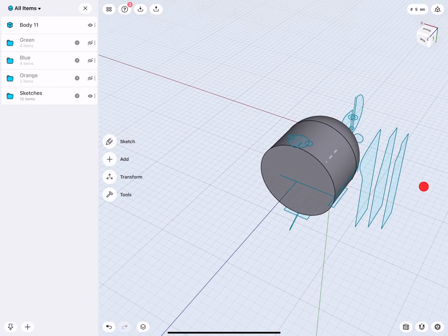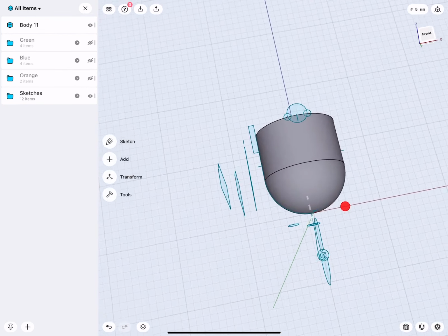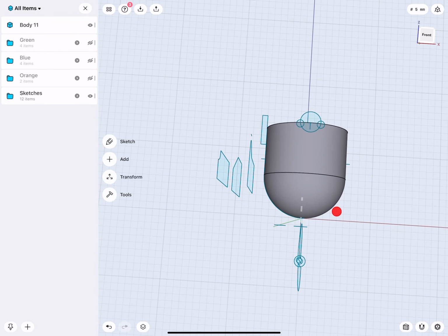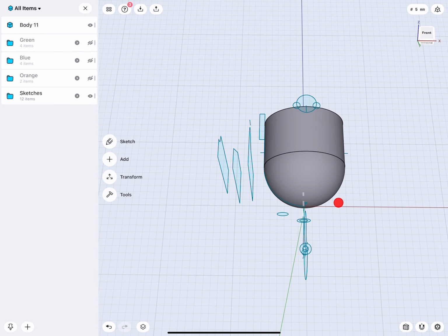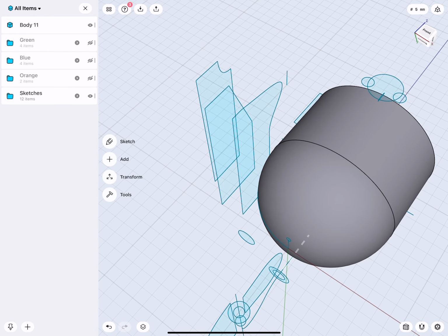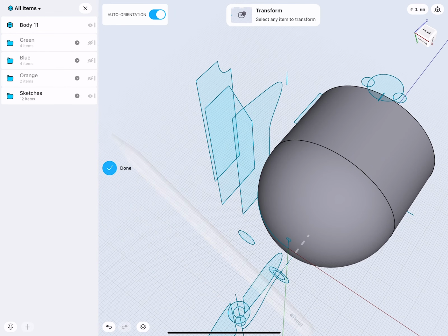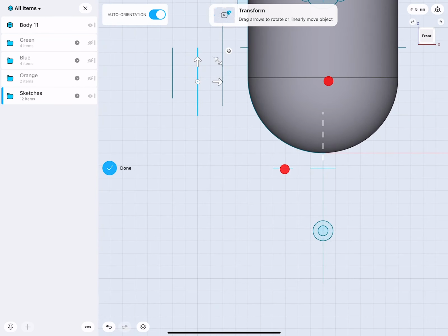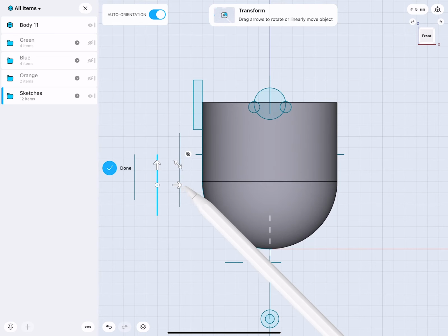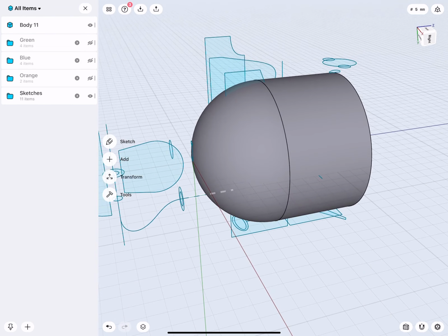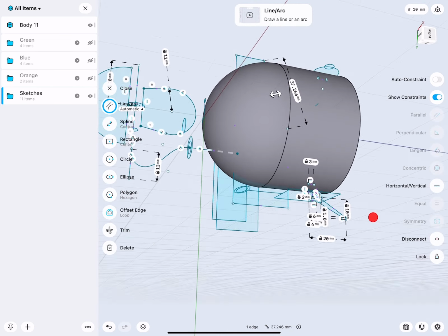At the end later, we want to shell this, but the shell command I will only do when particular features are already added to it, because I want the work to be very minimalistic. I don't want to have extra work. Now to cut actually this face into it, this is now where the move command will come in very handy. I select the sketch, go to top view, and then move this in there. Perfect. Now this is actually at the center.